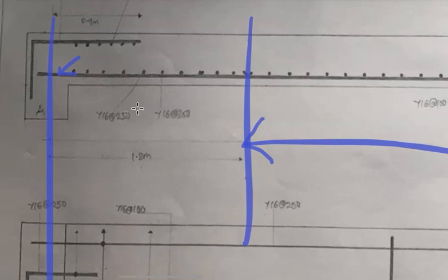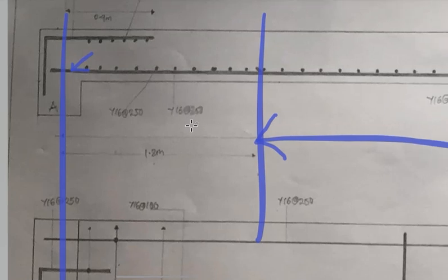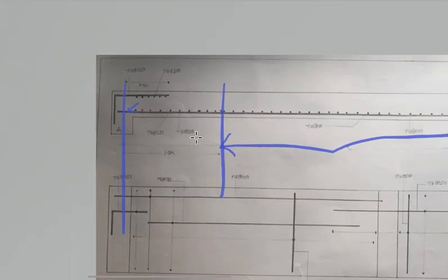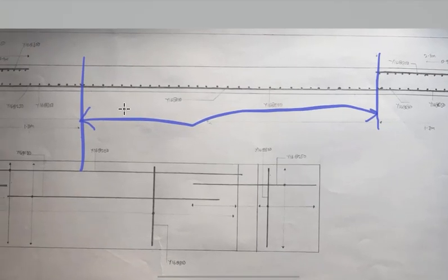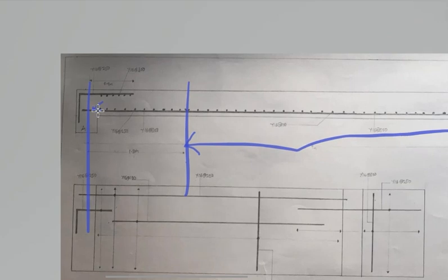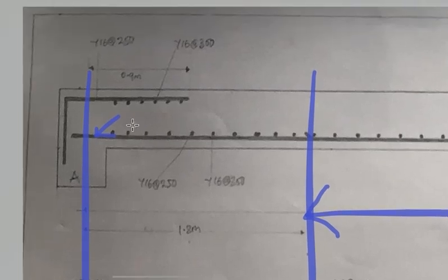But for this part, we are only going to be taking half of it, because we can't extend the whole area of steel across the slab, because we really don't need them at the supports, because there is literally zero to no bending moment at the supports. They are mostly negative, meaning that you need those reinforcements at the top. But since you've done that, remember this is a simply supported slab, meaning it is only resting on the beam, on beam A. So that is why we in fact don't need those areas of steel. They are not required, so we are just taking half of it, as you can see here.